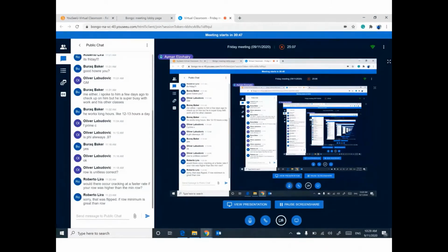So we maintain minimum reinforcement to eliminate all of this after construction. Your value of rho must be higher than the minimum value to keep the beam safe against the serviceability limit state, which is cracking. We will talk about this later.